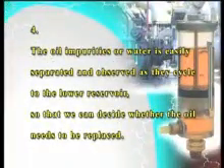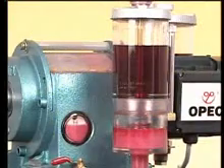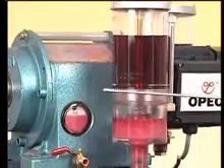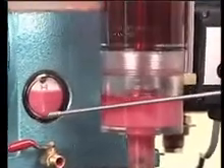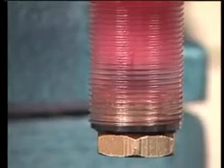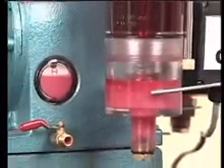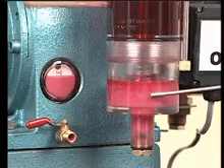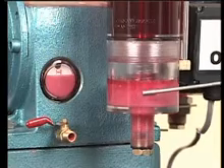The oil impurities or water are easily separated and observed as they cycle to the lower reservoir, so that we can decide whether the oil needs to be replaced. If water goes into a lubrication housing, we can see from the oil inspection window that the oil and water are emulsified together after a long time of mechanical running. When the oil mixed with impurities and water cycles to the lower reservoir, the separation of debris takes place at the collection tube due to their different densities in the half-rest state. Therefore, we can understand the quality of the oil inside the machine and decide when to replace it.